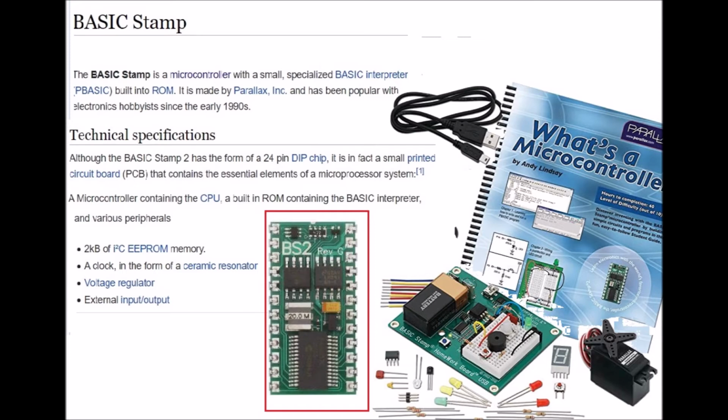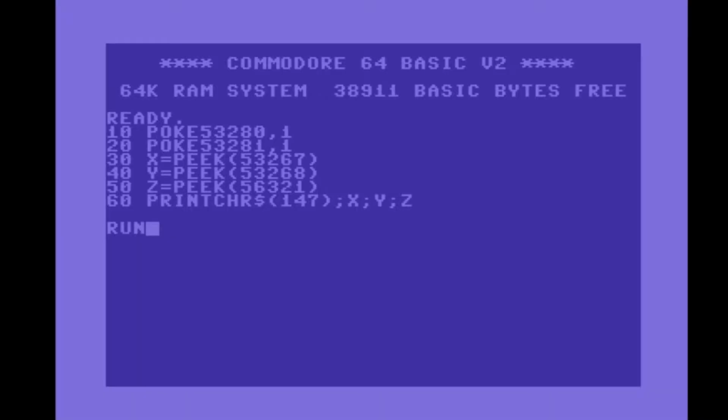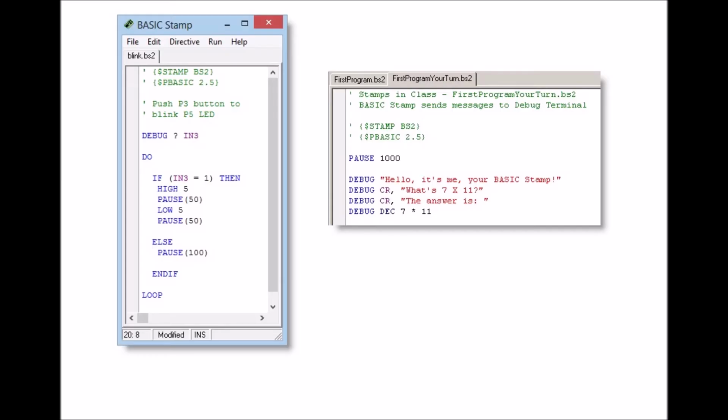Programming. The Basic Stamp is programmed in a variant of the BASIC language called PBASIC. PBASIC incorporates common microcontroller functions including PWM, serial communications, I2C, and one-wire communications, communication with common LCD driver circuits, hobby servo pulse trains, pseudo-sine wave frequencies, and the ability to time an RC circuit, which may be used to detect an analog value.